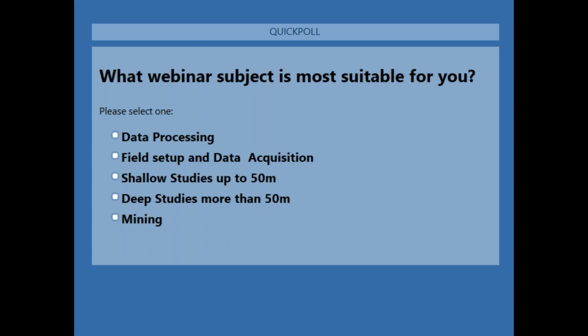So in that case, you will have good lateral data coverage. But in the resolution sense, always consider, whether vertical or horizontal, that the maximum resolution is half of the electrode spacing.